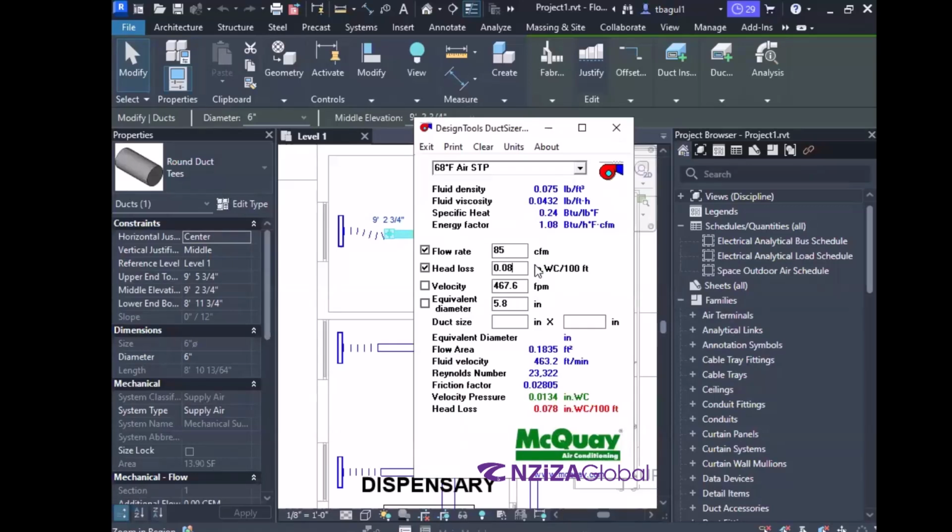The regular ducts are made up of galvanized steel, or aluminum if there is budget, right? But in the case of, let's say, commercial restaurants, where we need a heavier material for exhausting the grease from the kitchen exhaust hood, in that case the friction will be more. Is that making sense so far? Yes. So it will depend on the material type that we are using.